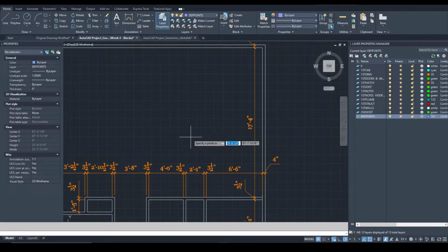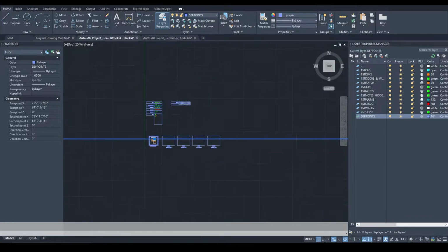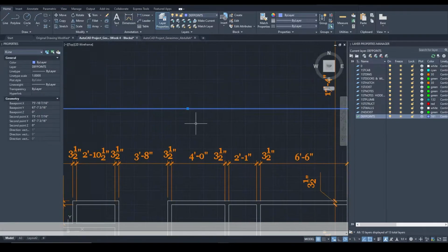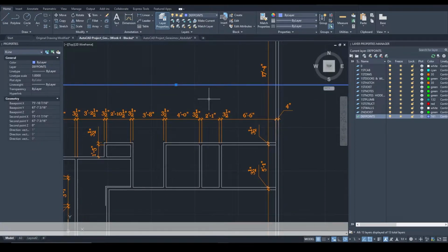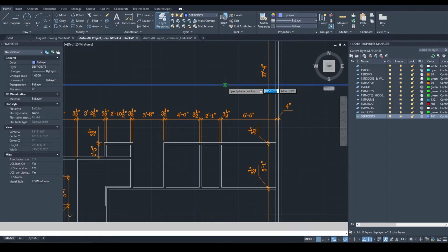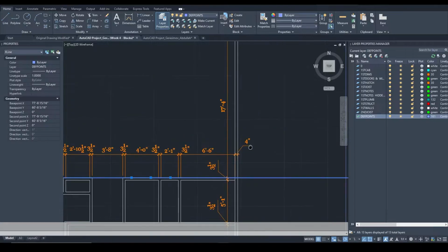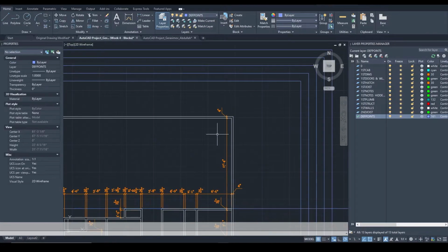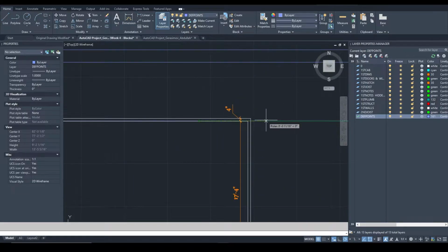XL, which is going to give you that layer, that line. And if you do everything correctly, you should have a straight line that never ends. No matter how much you zoom in or zoom out, it will never end. This is a reference line. Since it is in a def points layer, it's not going to be printed, but it's helpful for you to have those lines for the purpose of alignment. So for instance, right now I aligned that line 17 feet and 4 inches. The way you would start is type in XL, start with the interior portion of the exterior wall.